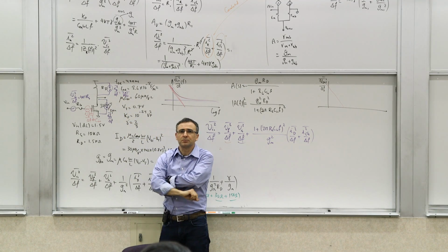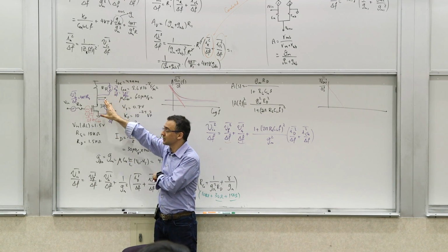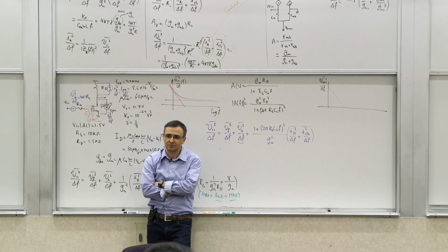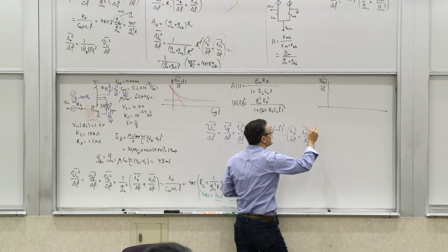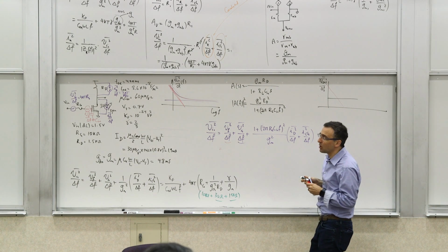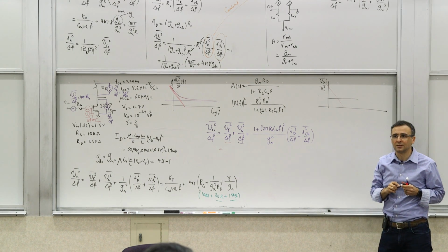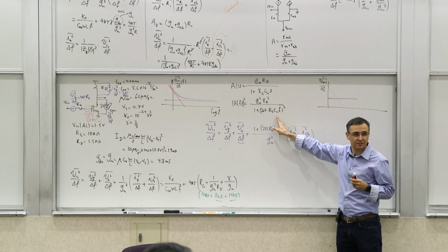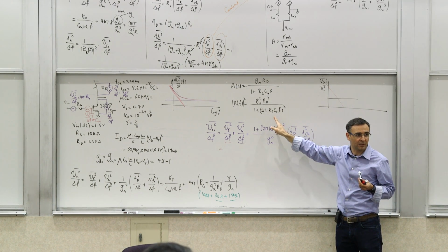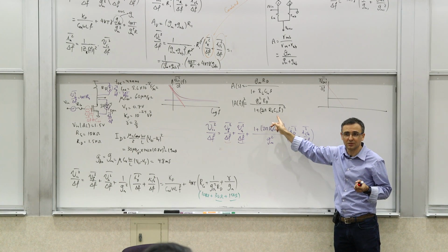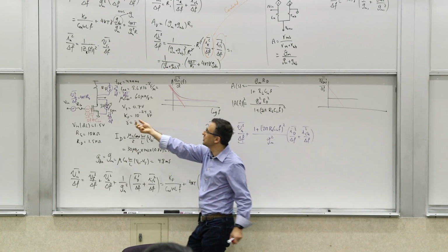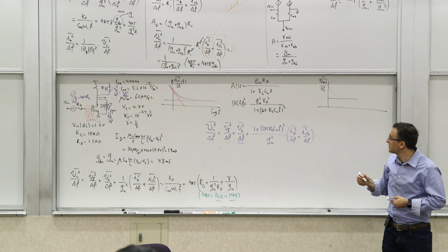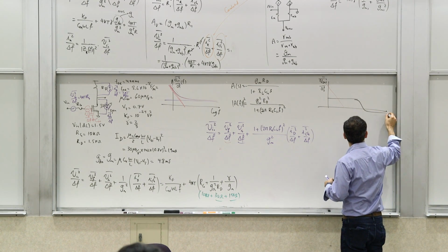So from the output perspective, these two are there. Right now we haven't introduced any capacitor there, so those two will stay up there, right? So they are there, but the contribution from RG, what happens to it? Once you hit this frequency, it starts dropping, because that's going through this transfer function. The noise due to RG is going to get attenuated at the input. So it doesn't get as much to the output, so you basically just drop here.